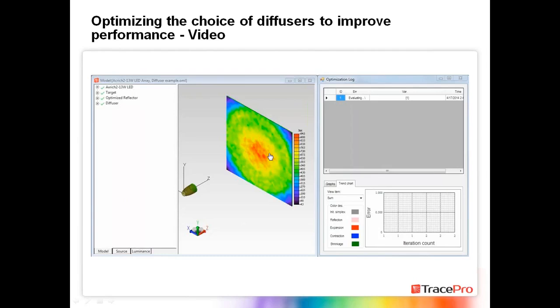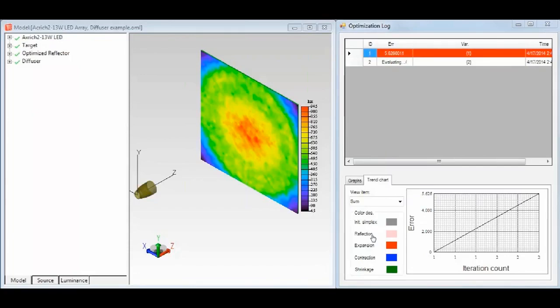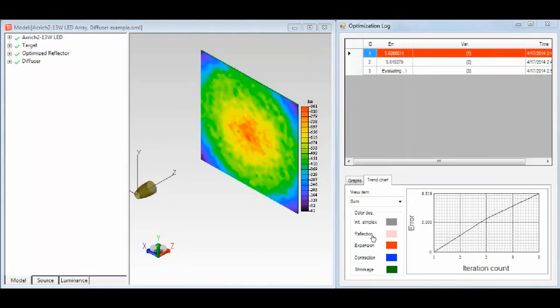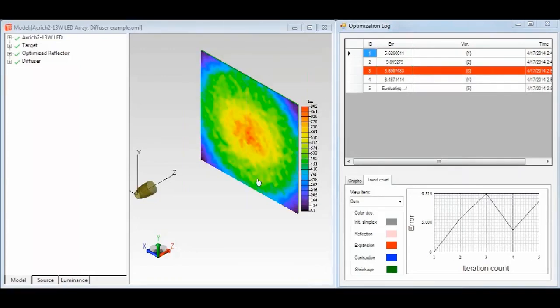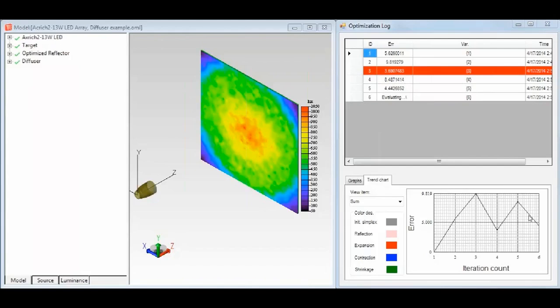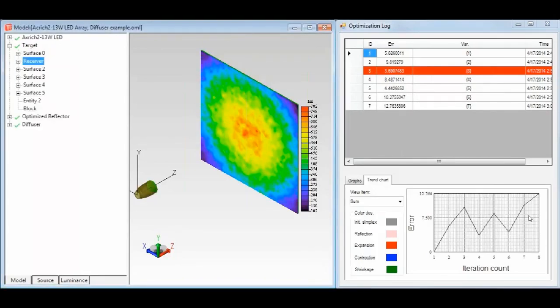And this is an option where I switch to that variable scanning method. And I define a variable. I'm calling it surface. It has a range from 1 to 7. If you remember previously, there's 7 properties in this catalog. So this is going to step through that variable from 1 to 7 in integer values. And then the last step is writing a small bit of macro code. In this case, it's only 4 lines long that applies that property to the correct surface and then iterates through the different property names and then refreshes the model each time.